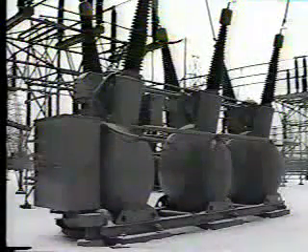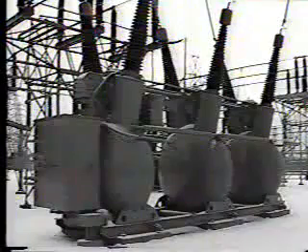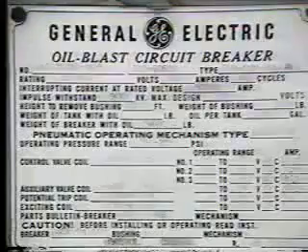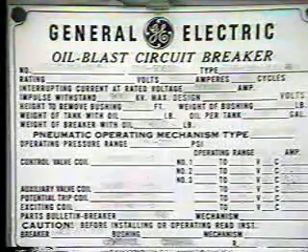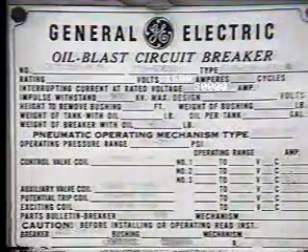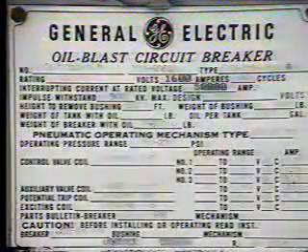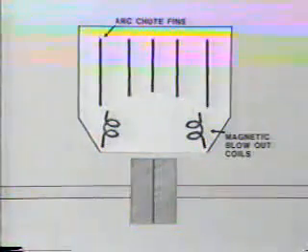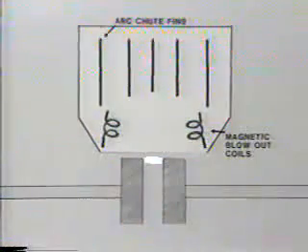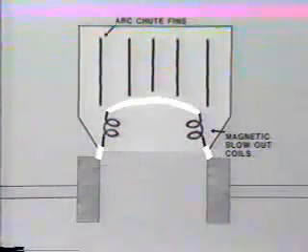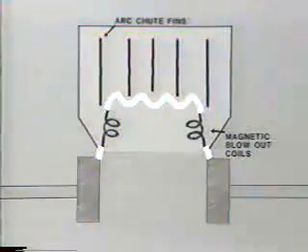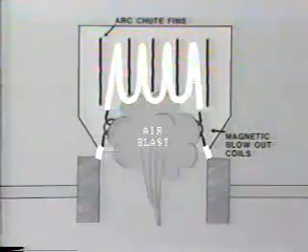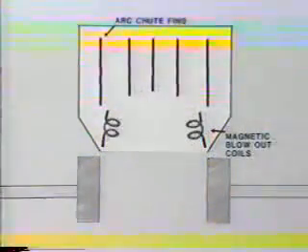Conversely, the circuit breaker would have little value other than as a manual switch if it were not coupled to protective relays. The circuit breaker is specifically designed to interrupt fault current, which may be 10 times or more than normal full load current. It achieves this by breaking the current flow in a specially designed interrupter. As the contacts open inside the interrupter, an arc is drawn. It is essential that this arc be extinguished immediately and the contacts thoroughly insulated from each other, so as to prevent a restrike, which could result in considerable damage to the breaker.